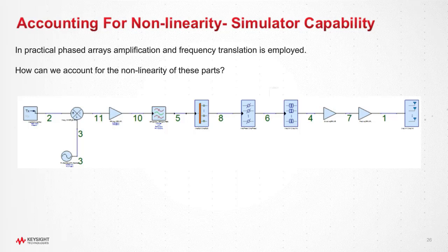As the signals pass through the nonlinear devices or the nonlinear components, they produce additional, undesired frequencies. When these undesired additional frequencies reach the phased array antenna, they also get radiated, even though not very efficiently. But the phased array itself is designed for a specific frequency or frequencies. So what happens to all these additional spurious products that arrive at the phased array antenna?